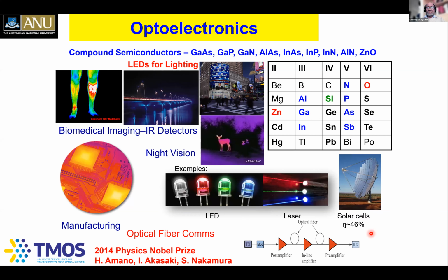So once the efficiency exceeded 40%, people started thinking about where they can make use of these solar cells in terrestrial applications. But as I told you, these solar cells are expensive, unlike silicon. And that's where people have been trying to use these for so-called concentrated photovoltaic systems, where they use the solar dish, essentially parabolic mirrors, and really focus the light to the central focal point here.